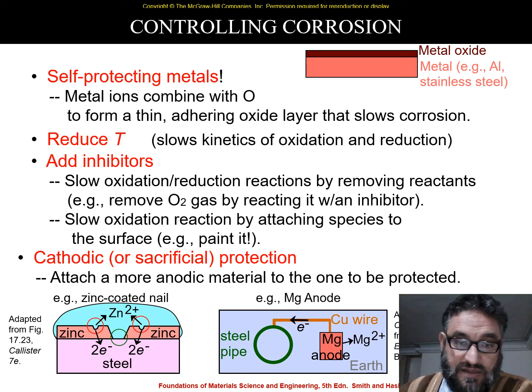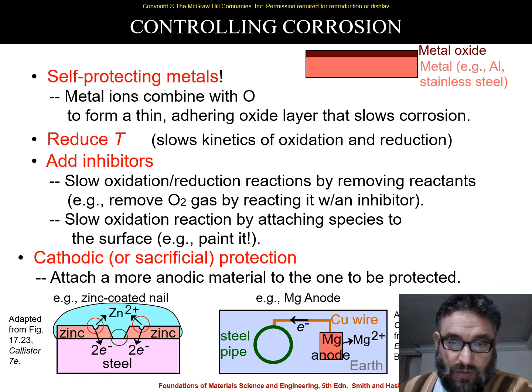And this kind of configuration also can be used here nearby the pipelines. We put an anode like magnesium or zinc, and we use a copper wire for connection.